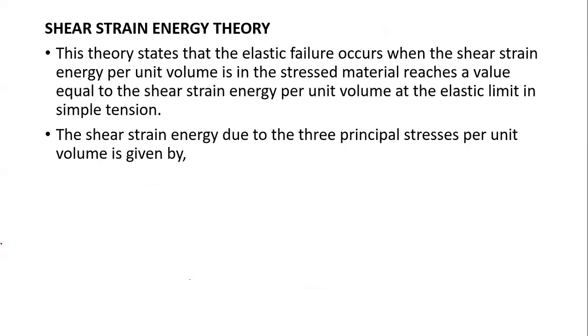Now with this one, when does failure occur? Only when the strain energy per unit volume in that material reaches the strain energy at elastic limit in simple tension.